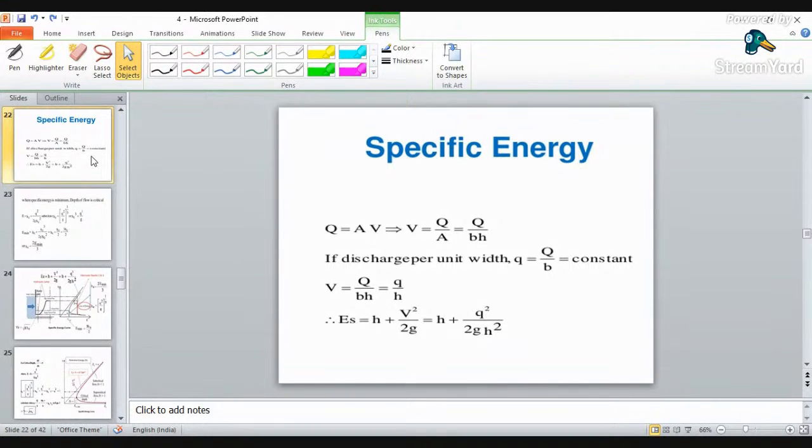In subcritical flows, the flows are definitely deep, and the velocities are slow or you may call it constant. But in case of supercritical flows, the depth of the section will be shallow. They are not as deep as subcritical flow and the velocities are quite fast. Supercritical flow will have a low potential energy and a high kinetic energy.